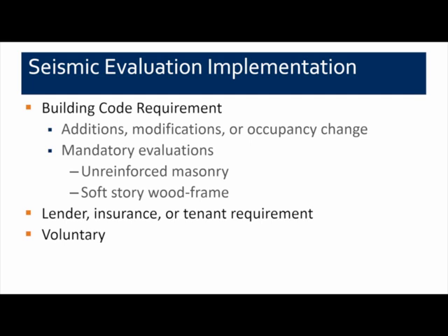There are some conditions where the local jurisdiction would have some mandatory evaluations. This might be for conditions identified as unreinforced masonry or a soft story wood frame structure, two common types of buildings that require an evaluation.